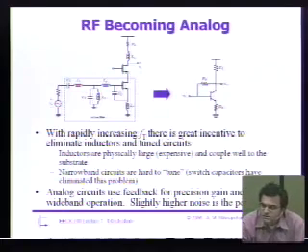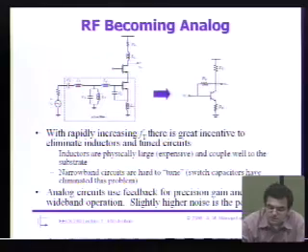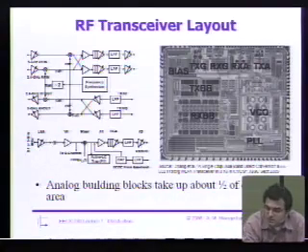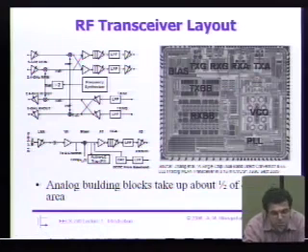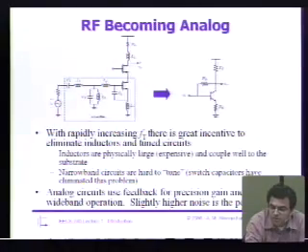Why not use inductors? They take up space? Yeah, they take up a lot of space. If you look at this layout again, you can see these little empty spaces where this inductor is. That's a lot of area. And you're also pretty much prevented from putting anything inside or around these inductors. You like to keep them clear. So the typical area for these inductors at these frequencies might be, let's say, 150 micron by 150 micron. So that's quite a bit of area.